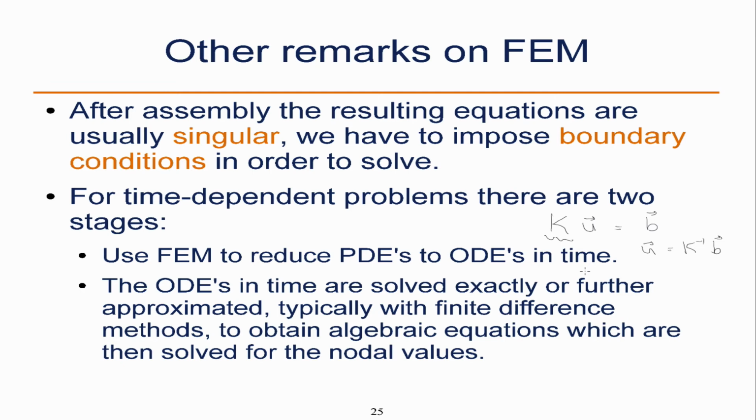if you're solving time-dependent problems, then you truly have a PDE. This is the case if you're an undergraduate in petroleum engineering, you took a course in reservoir simulation where you solve a diffusivity equation. That's a PDE, right? So you have to discretize in space and time. And usually what's done is that we discretize in space via finite elements, and then we just discretize in time via finite differences. Okay.